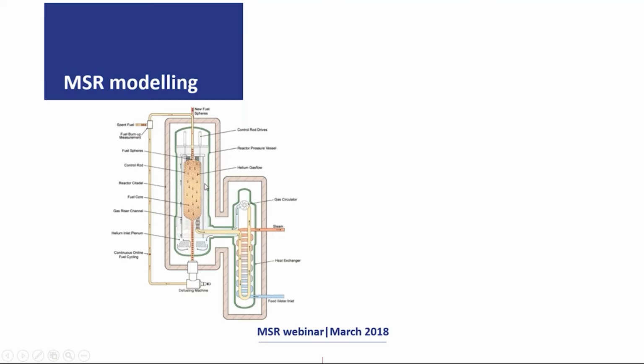This might be to cool down the reactor pressure vessel, and then it will go into the core, flowing down, going to my steam generator, changing heat, and then going back again, flowing up through my cooling passage, and then into the core. So this is just an example to explain to you how we go from here into a model that we'll be able to simulate in Flownex.